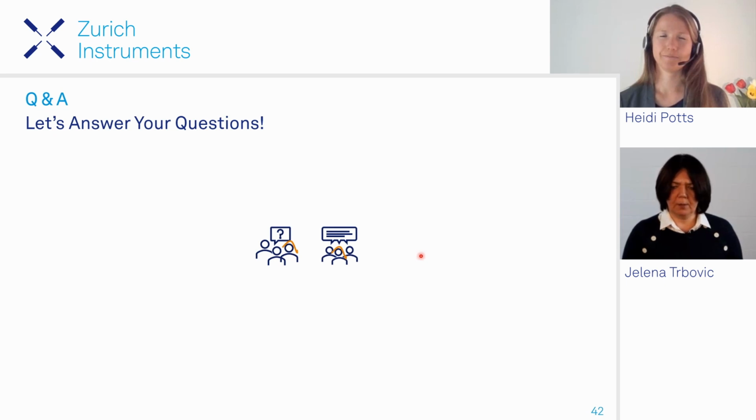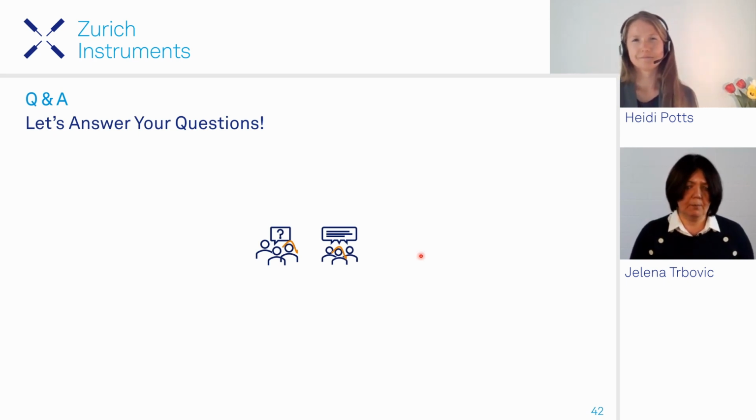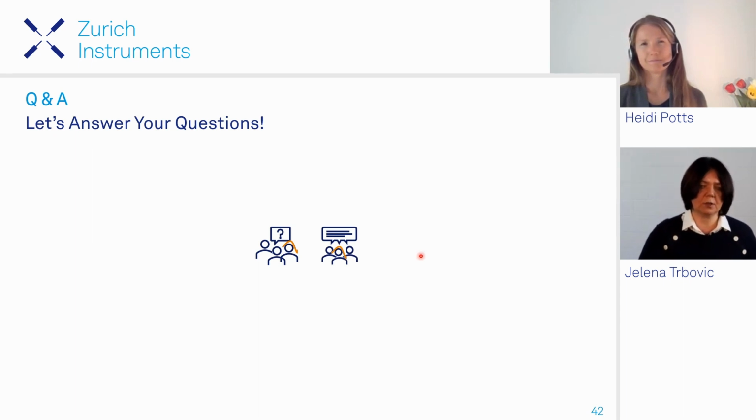Thanks a lot. Let me look into several questions that came for me. There was one question on the current or voltage preamp for the lock-in. Yes, of course. These preamps are regularly used, definitely for low temperature measurements. These preamps are placed very close to the chip, so it's a cold preamp.